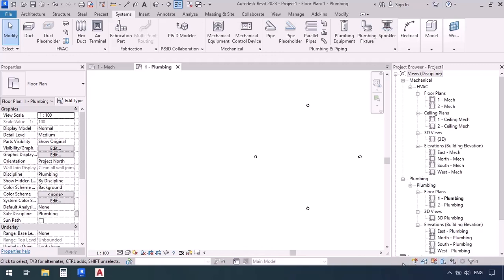And also on the right of this bar, we have some tools by which we can control the selection of the different items. For example, I'm going to want the pinned items not to be selected. It really comes in handy in such cases. Or I might want the linked items not to be selected. So I can control and manage the selections by going to this part right here.